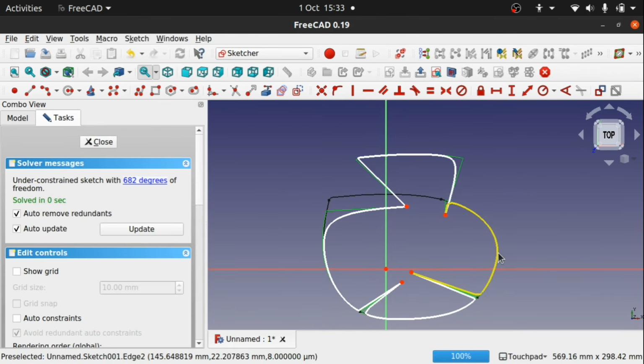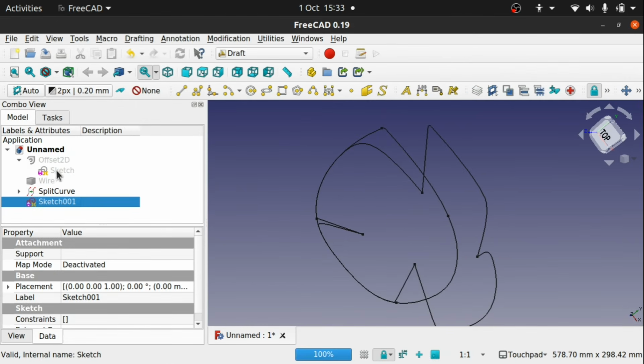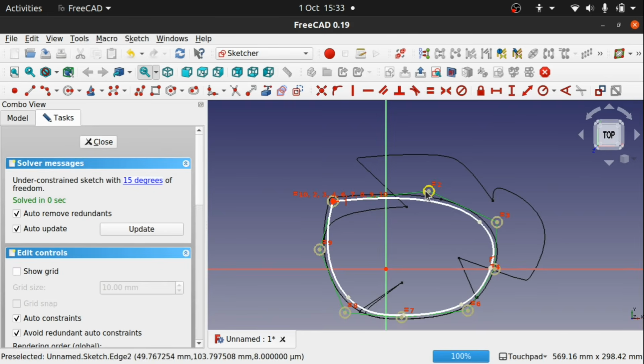We've got more pliability over it, but come back to the original sketch, and you can see we've got these nice node manipulators here to manipulate the curvature. This is all to do with that whole conversion back to a B-spline. And you'll find this with importing SVGs, you'll have these curves in there and trying to manipulate those curves, sometimes it's just best to retrace those.